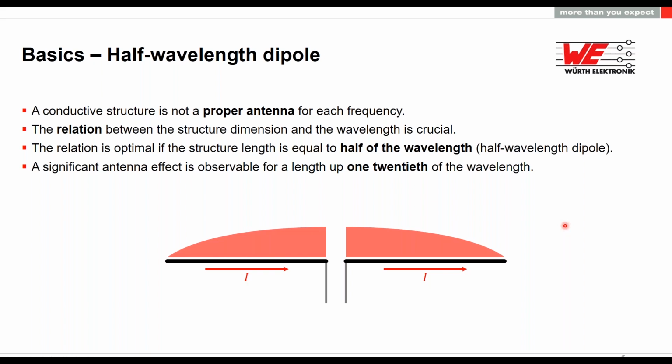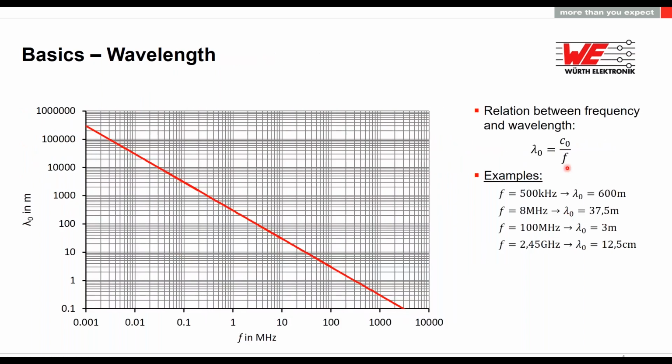So when we are having problems in our device and we are measuring different noises that are being radiated from our device, we just need to see the frequency of this noise, and then we can calculate, between half of the wavelength and 1/20th of the wavelength, the different distances using this equation, the different wavelengths that are dangerous from our device.